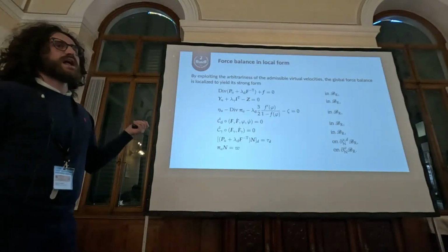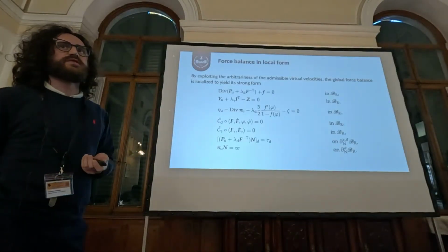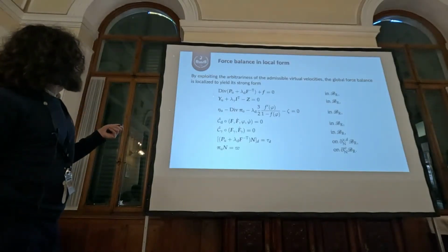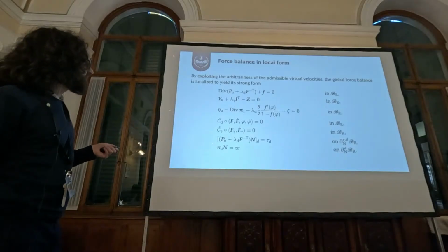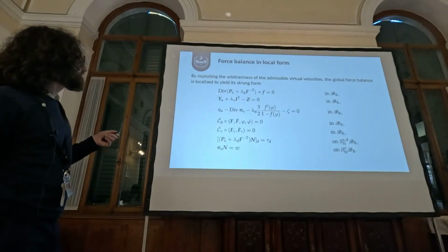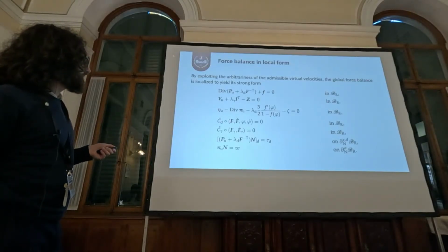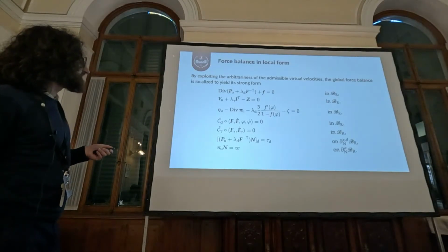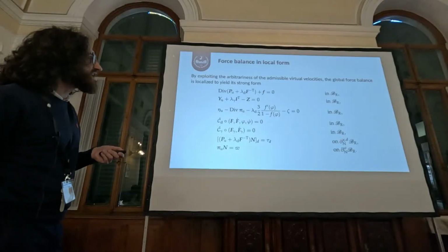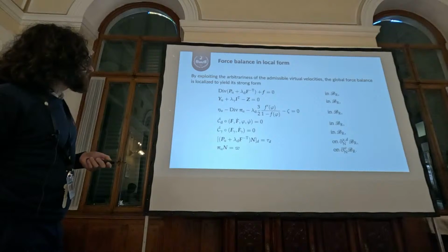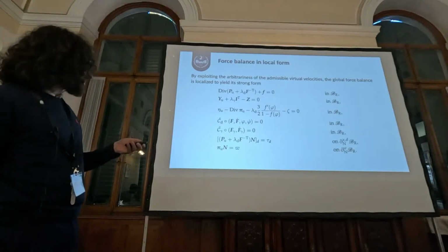By localizing the principle of virtual power through standard techniques, we can express the force balance in its strong form. So we have the equilibrium equations from the first three equations. Then we have the two constraints that, of course, have to be valid in all our domain. And then we have our natural boundary conditions.